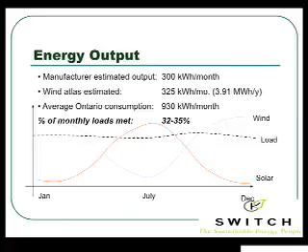And we take that 30 kilowatt hours a day, multiply that out, you get 930 kilowatt hours a month. So you get about a third of your loads met from that turbine. So I'd say that's the starting point you need to be at. You need to really understand your loads, and then you start picking your renewable energy to meet those loads.